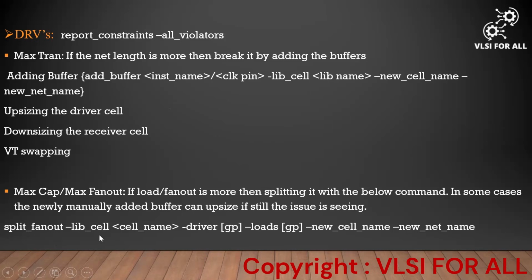Split fan out, lib cell, the cell name; the driver which has the cap issue, that pin we will provide here, and the loads driven by that driver, those load pins will be provided here. Then the new cell name and new net name. The cell which we are adding will be seen as a new cell name, to identify easily.